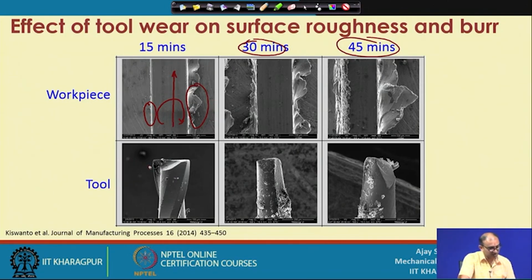So, this is the condition after 15 minutes, and after 30 minutes what is going to happen is that your cutting tool also gets worn, and because of that you end up getting more and more top burrs on both the surfaces. Now, the size of the burrs on the bottom or the down milling side is high, and you are also getting burr on the up milling side.